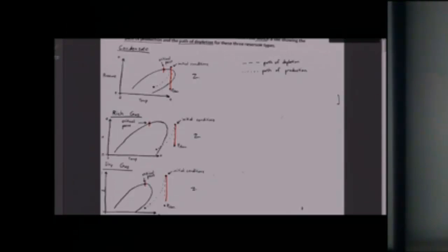Now, if the reservoir isn't permeable enough, it's impossible to maintain a pressure maintenance project. But the idea of a pressure maintenance project is to keep it above the dew point, to inject nitrogen, CO2, lean gas, anything to keep it above it, and sweep the rich gas toward the wellbore so that you get maximum liquid production.